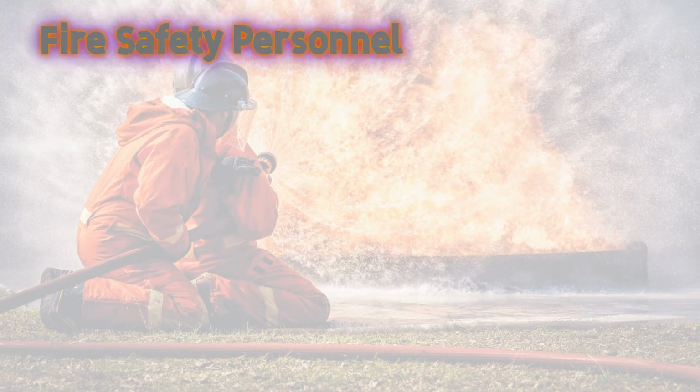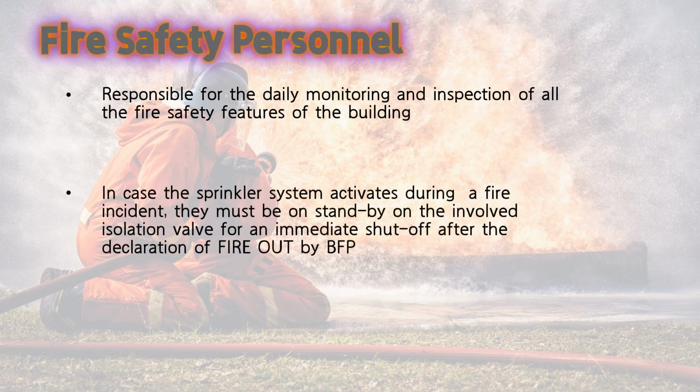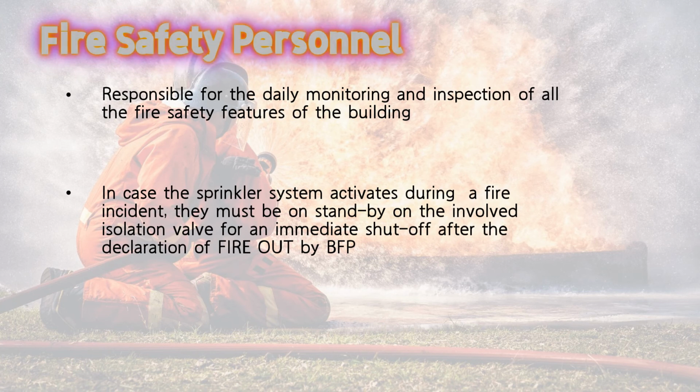Fire Safety Personnel. Responsible for the daily monitoring and inspection of all the fire safety features of the building. In case the sprinkler system activates during a fire incident, they must be on standby, on the involved isolation valve, for an immediate shut-off after the declaration of fire out by the Bureau of Fire Protection.